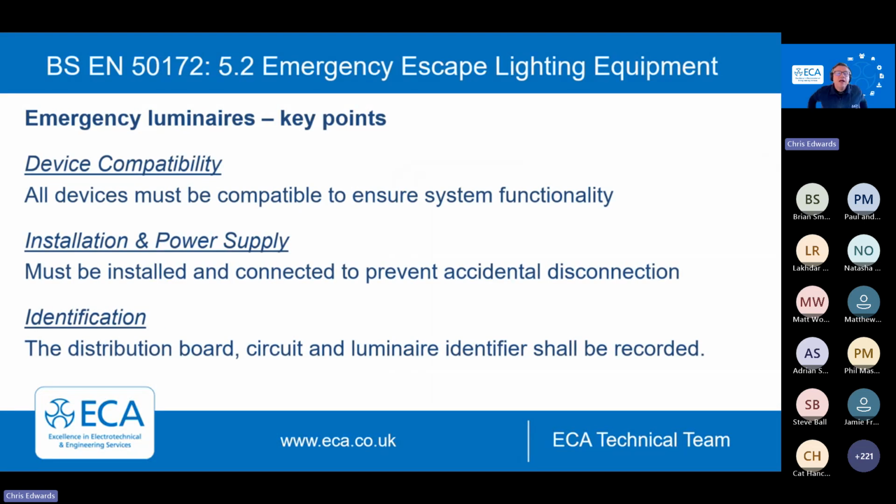Right, moving straight in. Section 5.2, emergency escape lighting equipment. A couple of generic points here. First of all, this is for if you're doing additions really, or indeed as a generic point if you're the designer. All devices must be compatible to ensure system functionality. It's a bit obvious really, but it's there in black and white now.